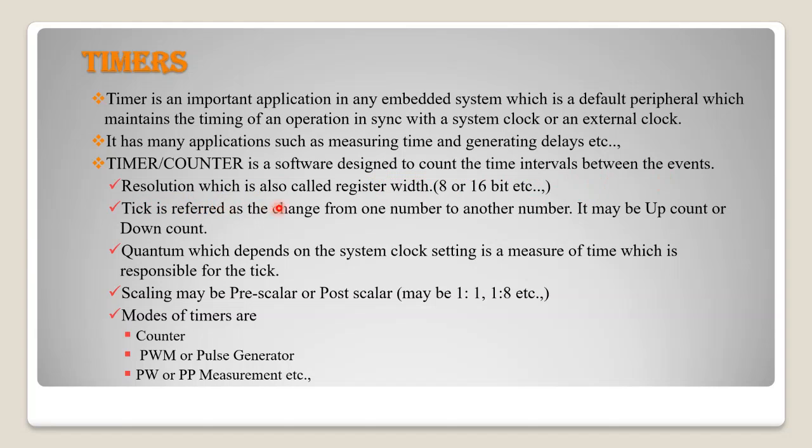Resolution, which is also called register bits. Tick refers to a change from one number to another number. It may be an up count or a down count. Quantum, which depends on the system clock setting, is the measure of time responsible for the tick. Scaling may be pre-scaler or post-scaler. Modes of timers are counter, PWM or pulse generator, PW or PP measurement, etc.